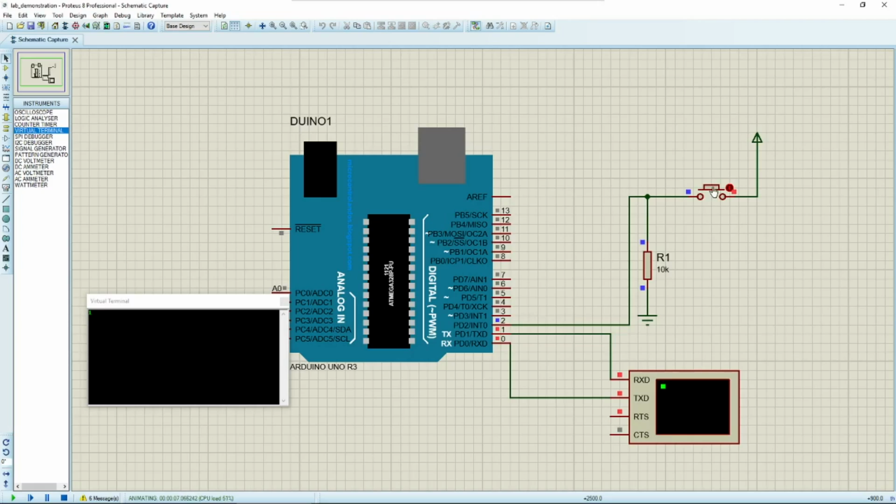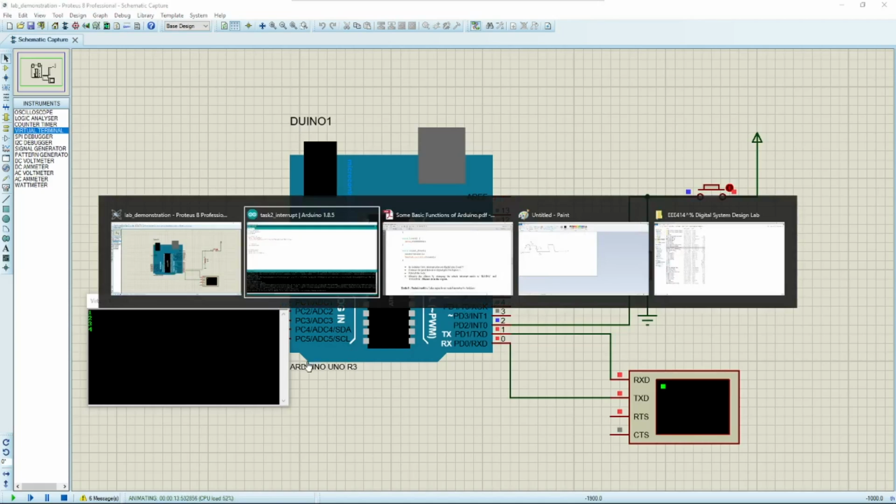That's why if we just click here, the count increased to 3, and if I press it again, now only 4 times we got, and if I release it, nothing, because when I released it was from 1 to 0, but we are performing our interrupt in rising mode.